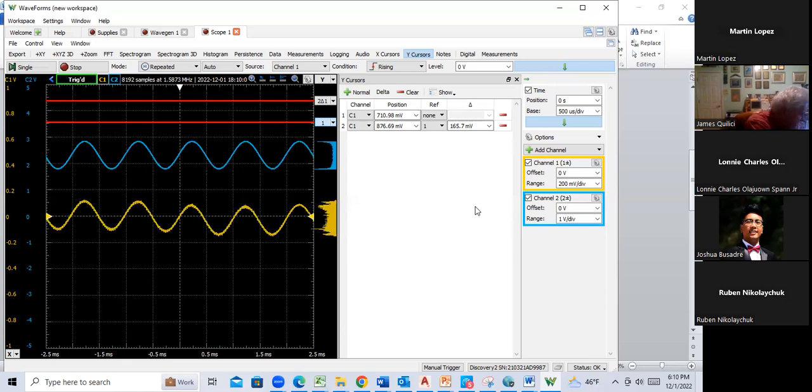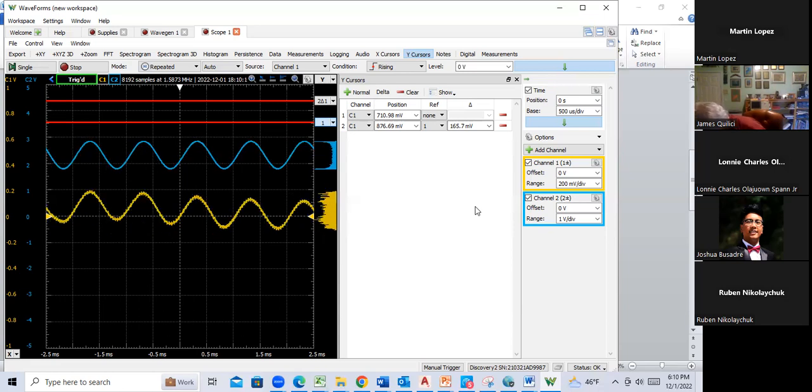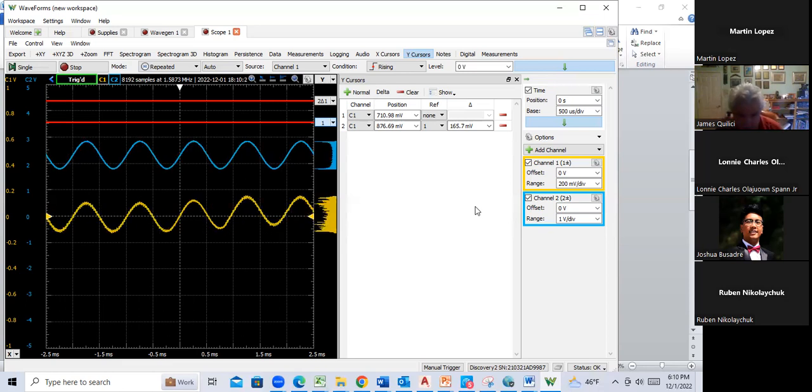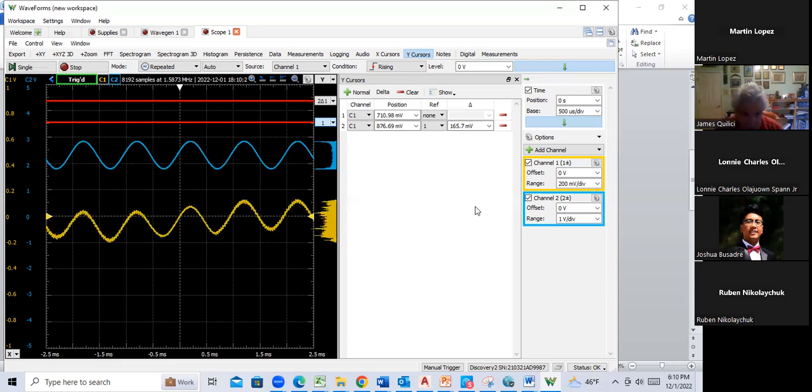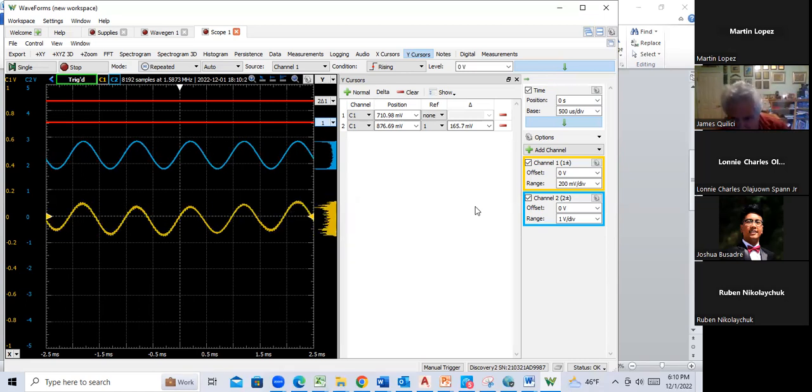Whenever you lay out an integrated circuit on a printed circuit board, one of the first things you do is put a bunch of capacitors between the power supplies and ground just to filter any noise. Okay, anyway. I think I got ahead of myself.